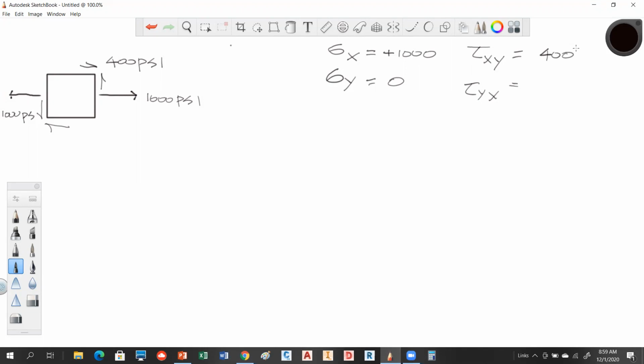And we're going to say that clockwise is positive. I'm sorry, counterclockwise is positive, and clockwise is negative. So this one is tending to turn this element that way, so it's positive. If you mess this up and reverse it, it doesn't matter. You'll get the exact same answers. It's just your circle's graphics will be different. This is the biggest deal right here. Once you get these, the rest of Mohr's circle falls into place.